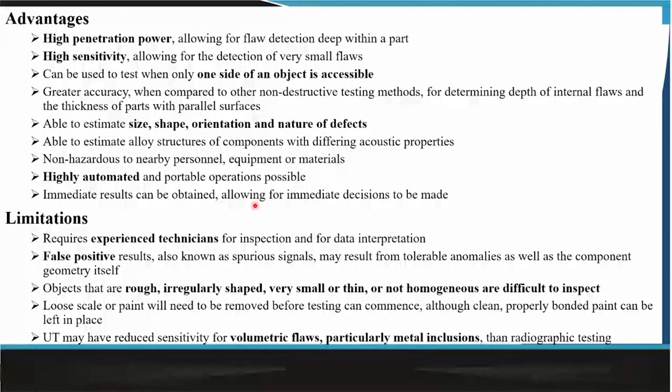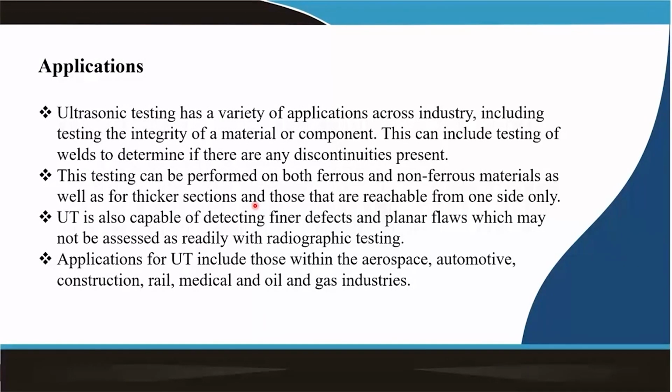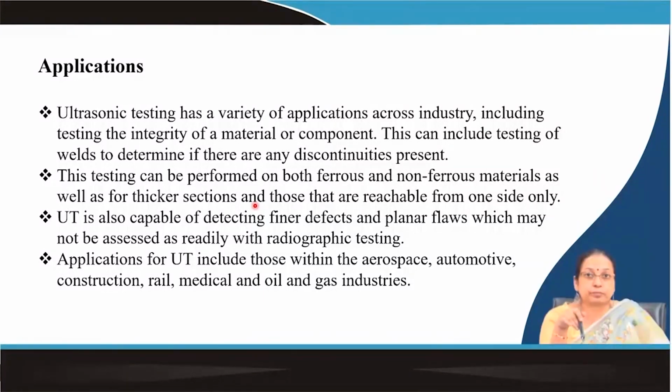need to be removed. It is very sensitive to surface discontinuities, but discontinuities in the subsurface regions far below the surface, like volumetric defects and inclusions, cannot be determined by ultrasonic testing. So, again, to some extent surface and a little bit of subsurface defects can be determined by ultrasonic testing. But it has a lot of applications in industry.